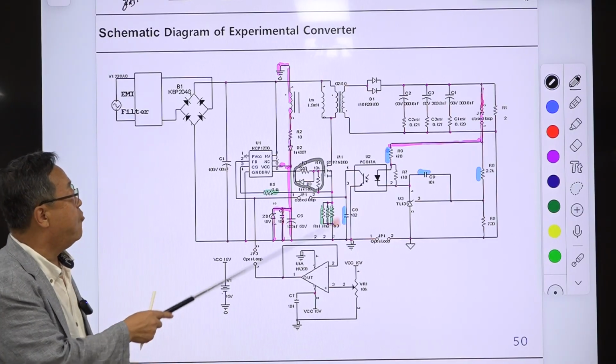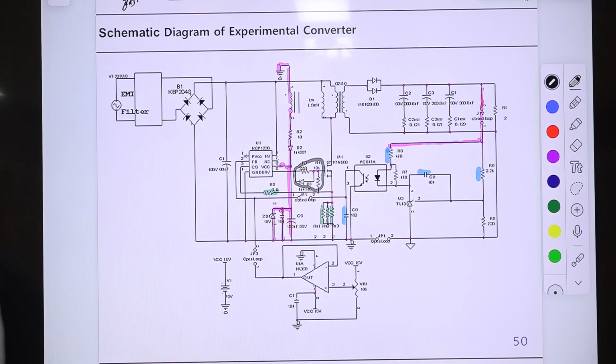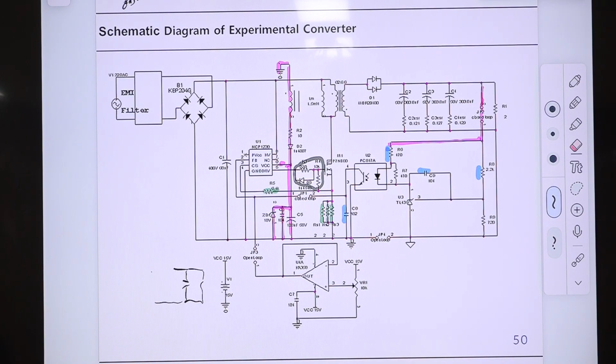So there is a filter here for the buck converter. This filter structure is obvious because we have L here, the output capacitor and the load here. This is split, because this is a low pass filter, but in boost and buck-boost converters, the inductor is coming in the front part.